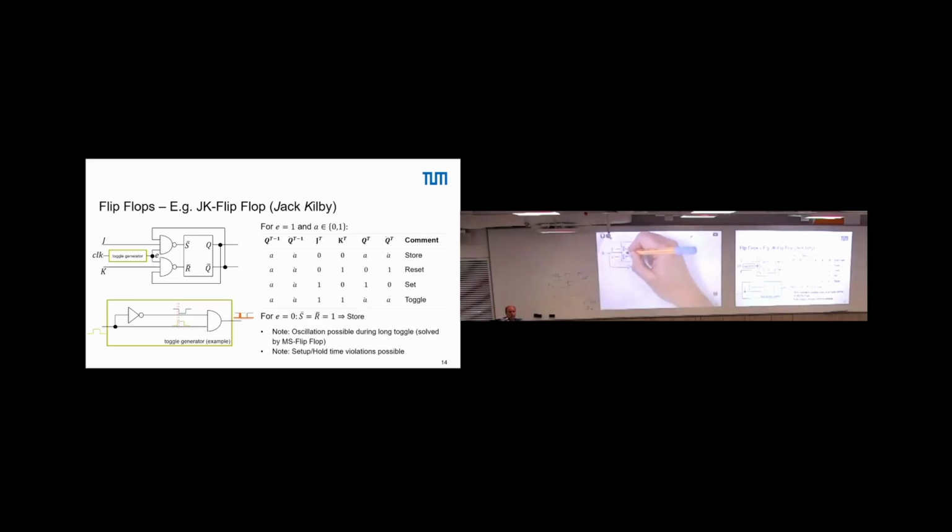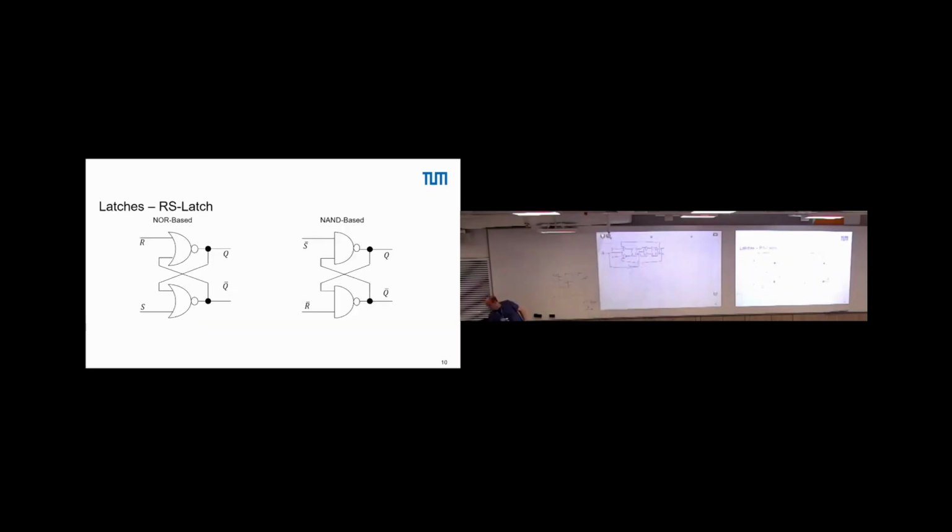Now, the propagation of the signals here into this inner node. There's a propagation time. Do you agree? So, this is not zero time, this is not a pure digital world, it's an analog world. So we need some propagation time from the input to here. If we switch our clock while something's propagating, we cannot reliably say what the internal state is, because not everything is settled. So maybe we go back here.